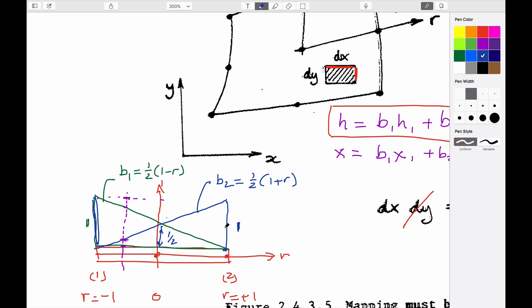And I'll leave it there because I see we're going too late. So next time what we'll do is we will talk about why we would do this, not for this very simple system, but for a real system. And the real system is two things. One is we want to use more complicated shape functions, as we've just alluded to. The second is that when we do our integration, we don't just use analytical integration, but we use numerical integration. And so both of those conditions are the kind of industry standards that COMSOL uses. And so that's our reason for exploring it.